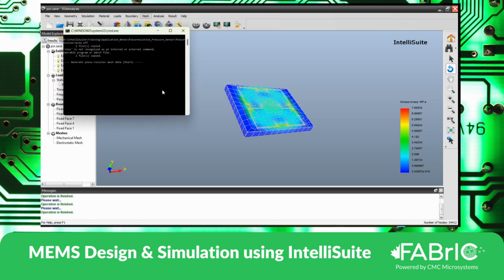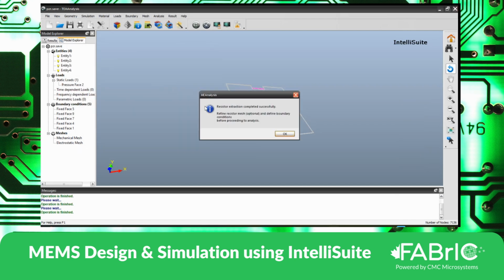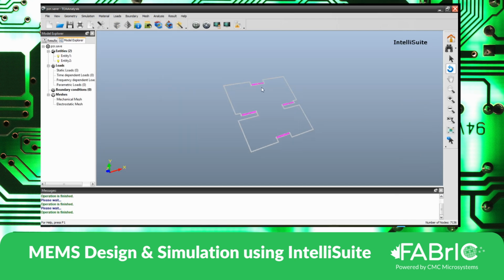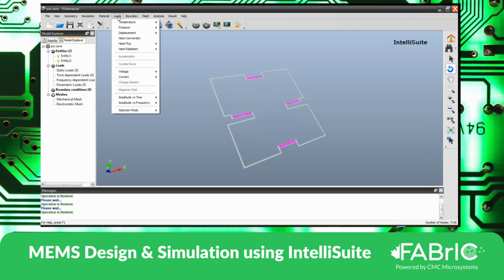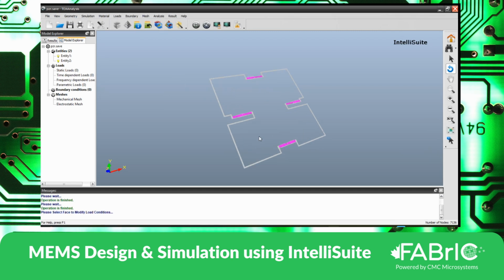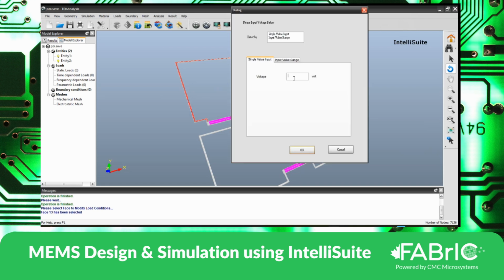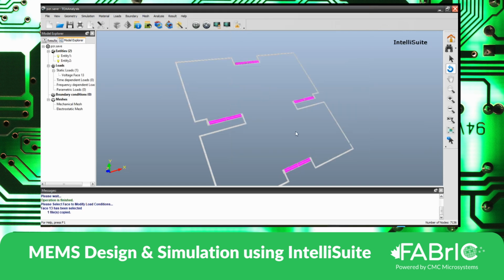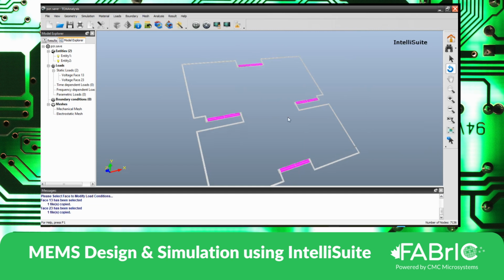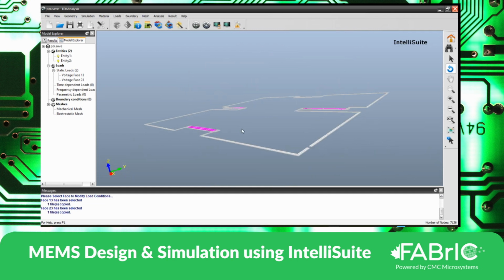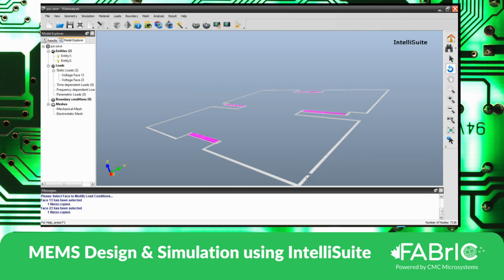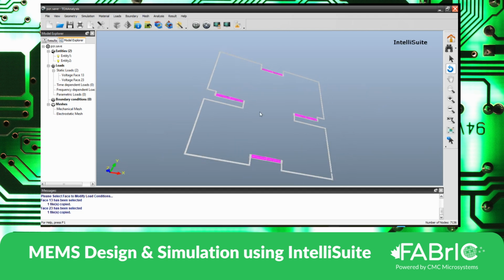Now I extract the electrical mesh, and this is purely electrical simulation. At the back end for this simulation, the stress data is recorded already. So I would apply 5 volts to this, and then I apply 0 volts to this point. Here you may notice there is a small gap between the two. It's not really connected. The same is the case with the Wheatstone network.